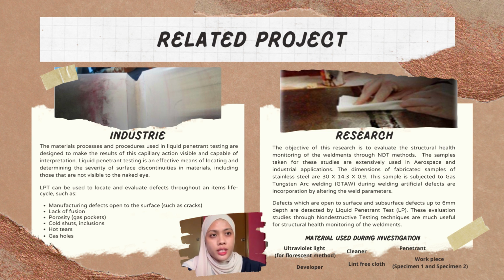The materials, processes and procedures used in liquid penetrant testing are designed to make the result of this capillary action visible and capable of interpretation. Liquid penetrant testing is an effective means of locating and determining the severity of surface discontinuities in materials, including those that are not visible to the naked eye.